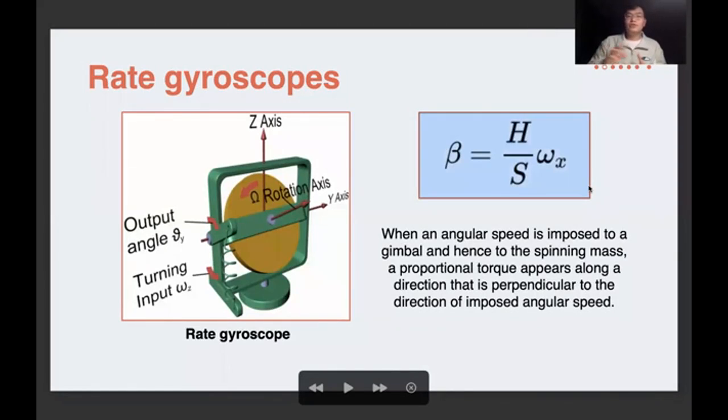I will briefly introduce the rate gyroscope, modern gyroscopes, and gyroscopes in navigation. The rate gyroscope uses the special properties, the fixed axis and the positions, to calculate the angular velocity in a certain direction. The rotation of the rate gyroscope around the axis is subject to elastic constraints. When the gyroscope torque is balanced by the elastic constraints, the output signal is proportional to the angular velocity.